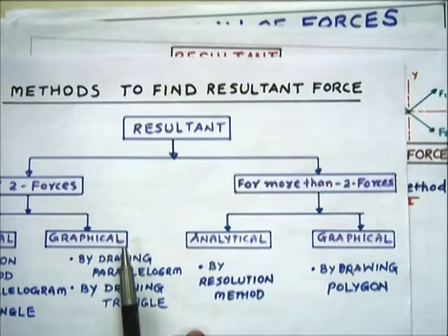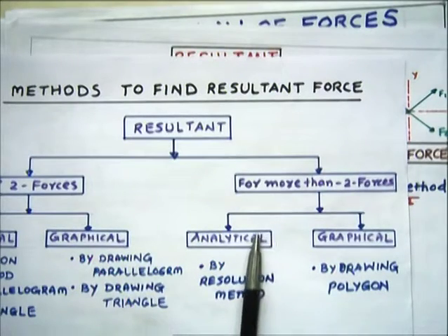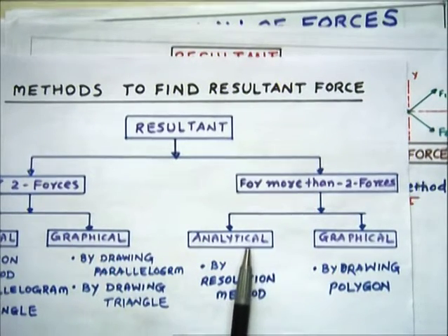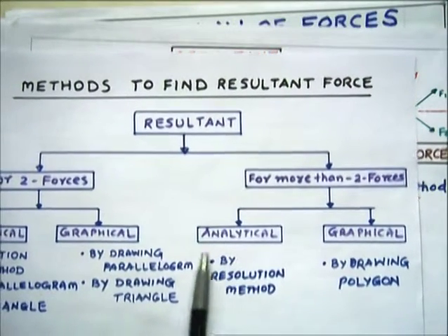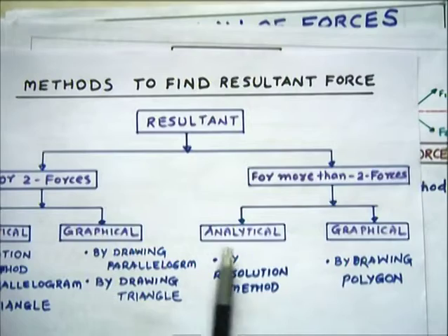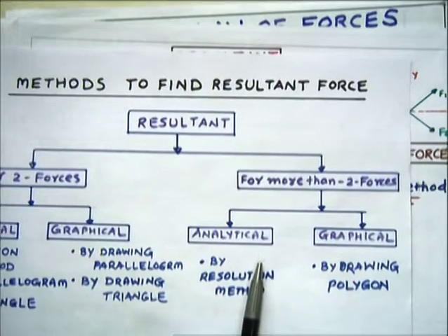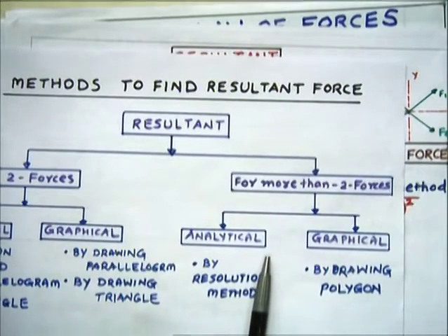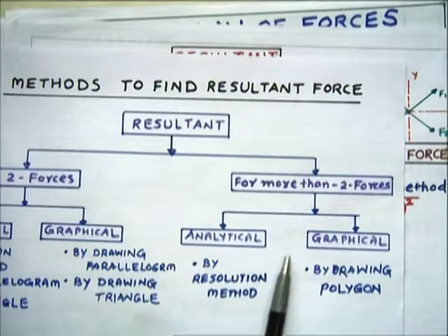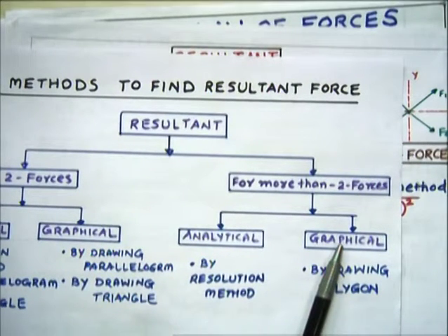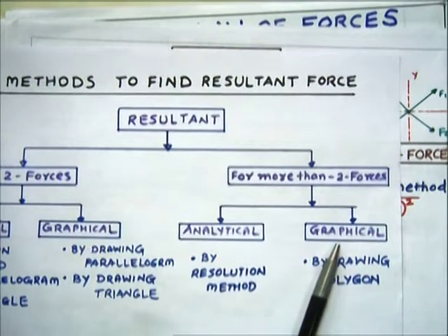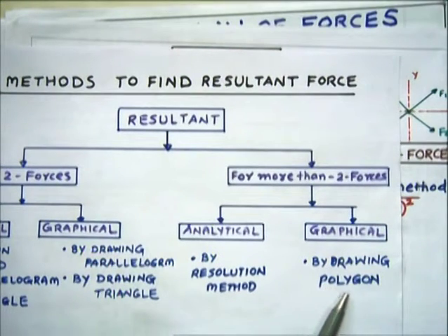For more than two forces, analytically there is a common method, which is the resolution method, which we use in the two forces case also. That is the resolution method, in which R is calculated by a formula. And for more than two concurrent forces we can solve it graphically by means of drawing a polygon, or force polygon.